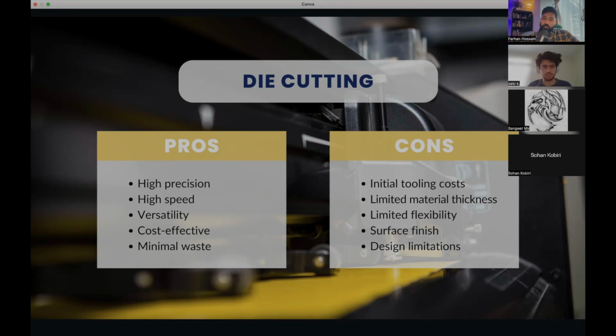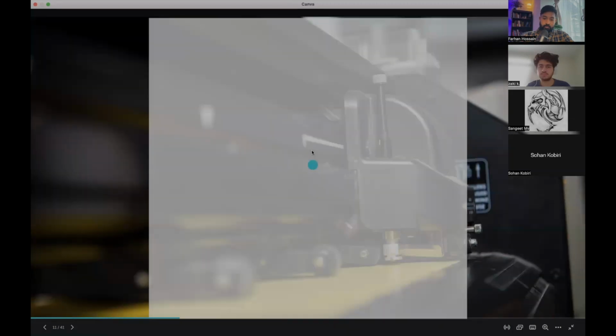And I think that's an important thing to remember, that this process specifically is for when you want to repeat planar shapes. But I'm looking around my desk and I can see that there are many planar shapes. So for example, let's take a look at this Velcro here. That's likely die cut, so it's just the shape that they cut out of a big sheet of Velcro, right? Does that make sense? Even this whole bag is likely die cut. It's an open bag that they die cut into this shape. You see where the seam is, and then they later process it to sew it into place. Cool. Now we can take a look at a video of this.